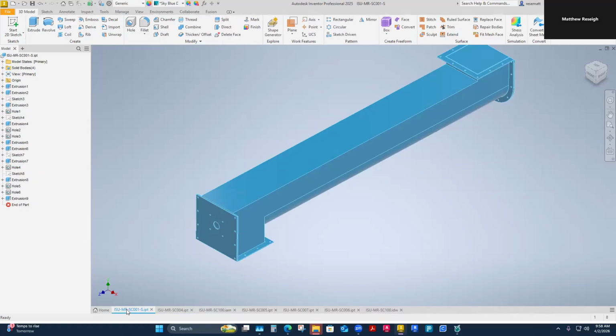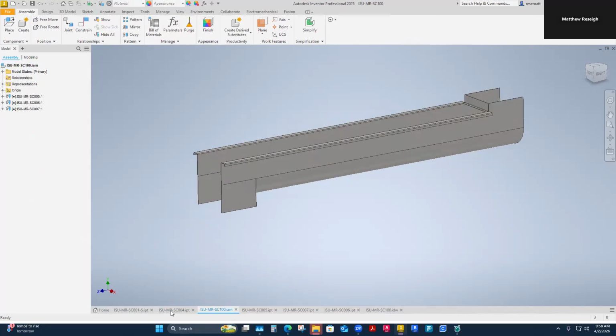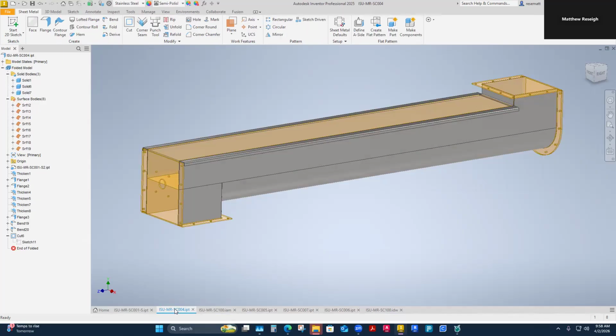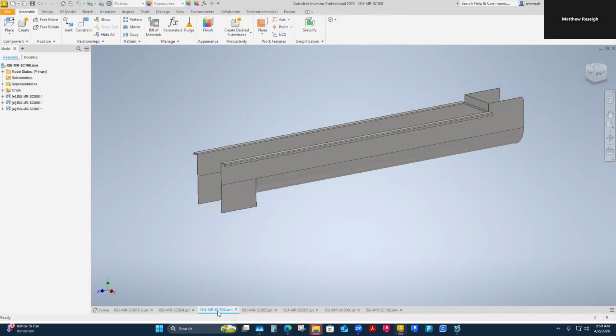This isn't going to end up on a drawing either. These are just control parts, how I'm manipulating my other parts. So these are just control files. This was the first assembly. That's why I saved this with the surfaces turned on, so I can identify what it is. And this one here is the first one that just looks like a normal assembly. And it is a normal assembly. It will have these parts that I can detail.